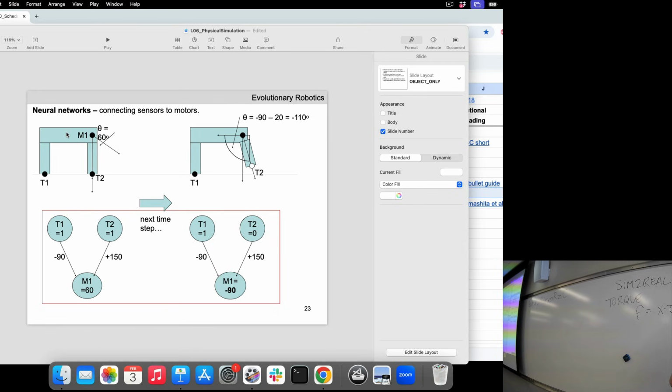What would happen if we ran an evolutionary algorithm that was trying to maximize f? What would we get? We'd get a robot, hopefully, that moves in the positive x direction. You get a robot with a lot of torque, need it or not. We'd get the opposite of what we wanted, right? We'd get something that's really, literally throwing its weight around, not what you want a safe robot that weighs 170 pounds to be doing. So this was a bad choice. Can we do better?